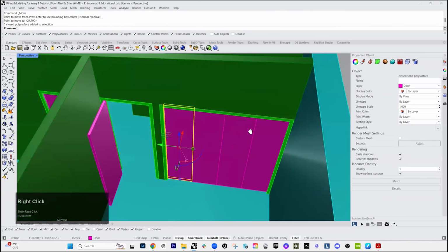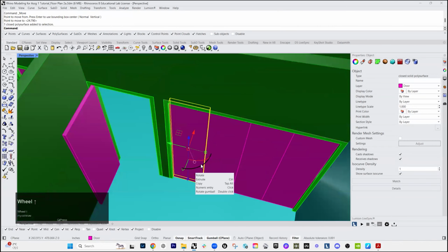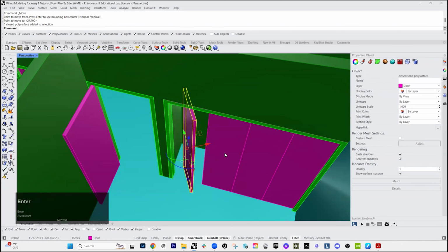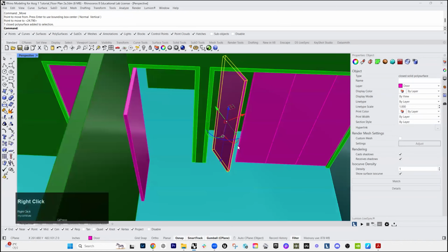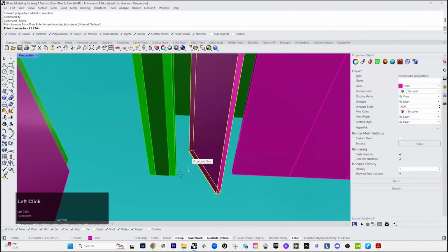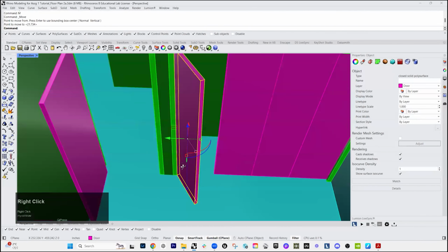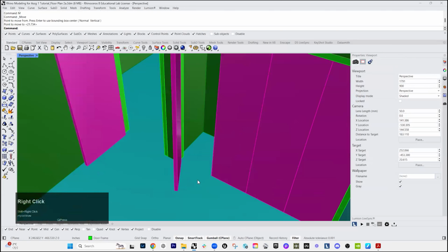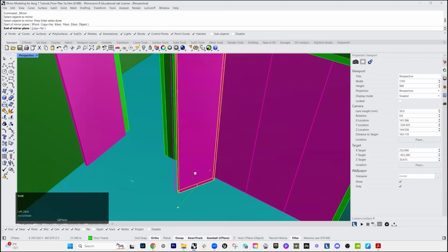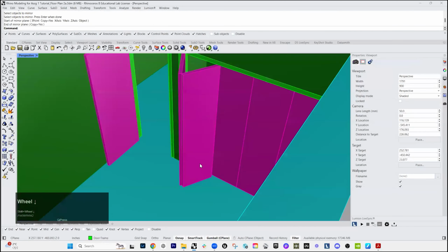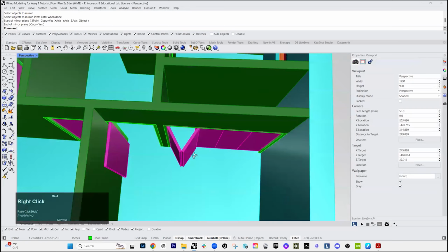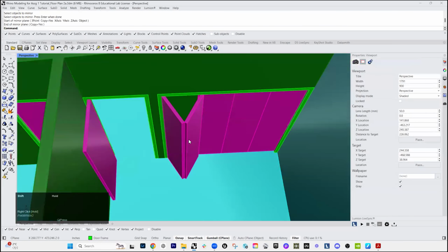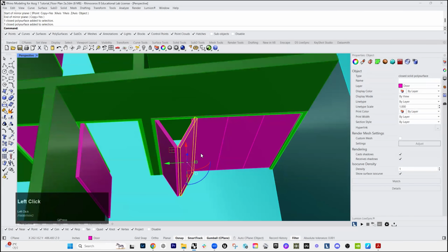So to do that in Rhino, again, it's quite simple. You just have to click on this blue arc over here. I'm going to type -60 for this. And then I'm going to move this corner to this corner over here. And I would just type MI, the shortcut for the mirror command, select this, and then press shift to draw straight construction lines to mirror this geometry to this side.